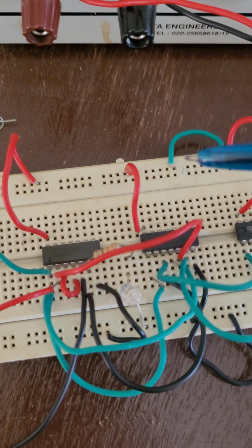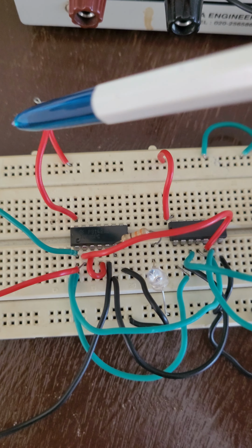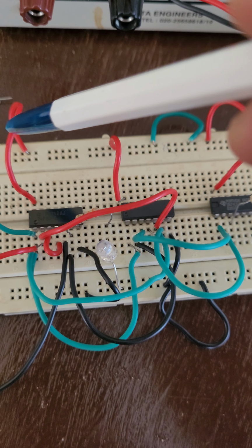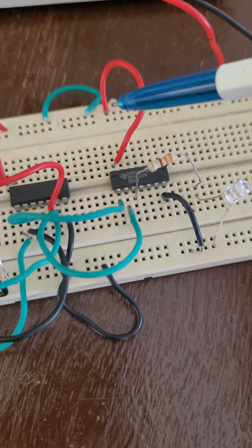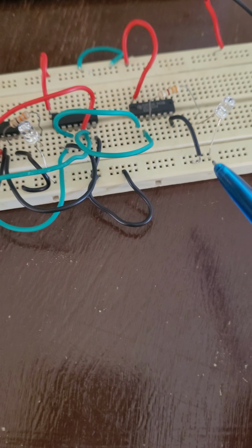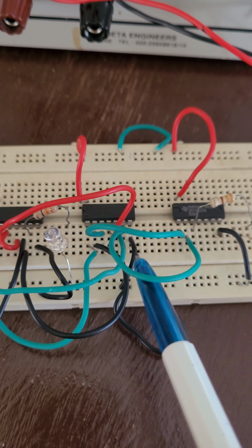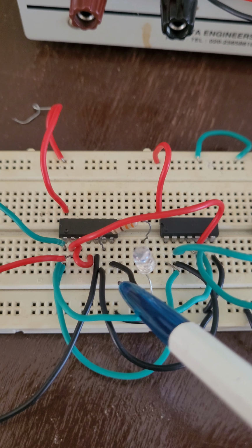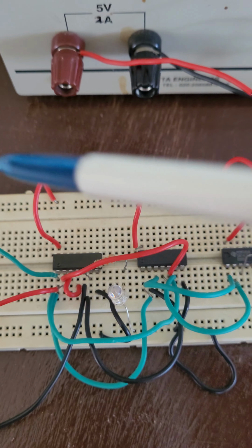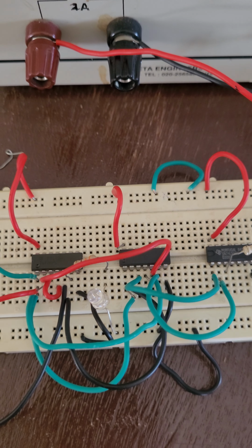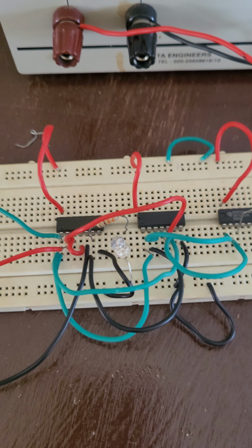Now, breadboard connection, you all are aware that pin number 14 of each IC has to be connected to the positive of the power supply. So this is positive, and ground for this is the black wire. This is connected to the ground. This is also ground, and this is also ground. So these black lines are connected to the ground, while these upper red ones are connected to the positive of the power supply. So these are the basic power supply connections.